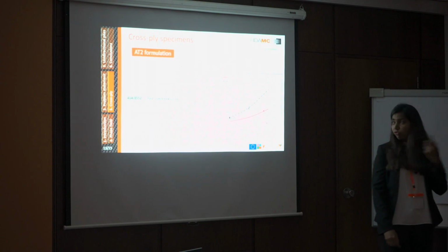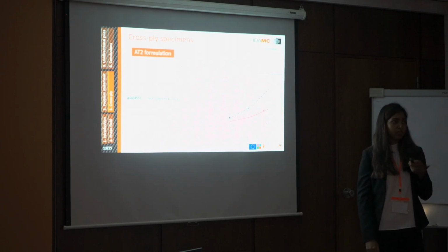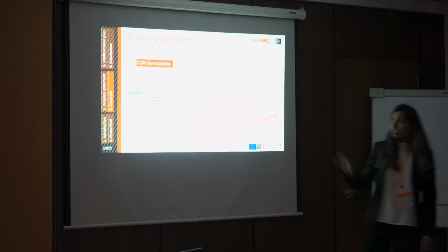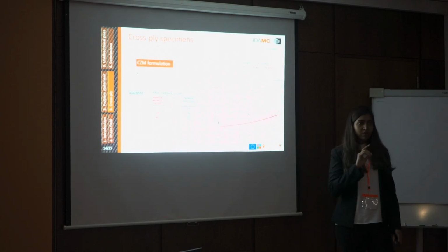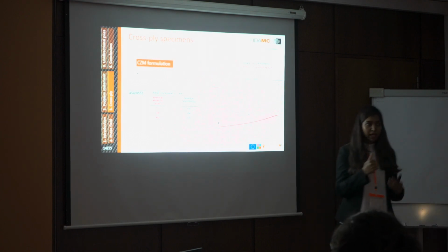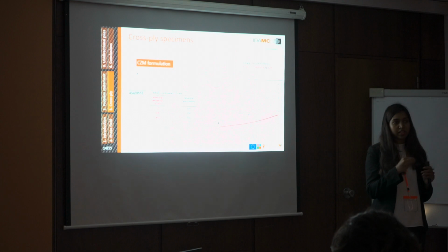We then finally checked the last formulation, which is the phase field cohesive zone formulation. In this formulation, we do not have the length scale as a material parameter but as a numerical parameter. The only parameter that we impose in the model is the tensile strength.